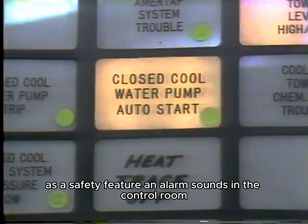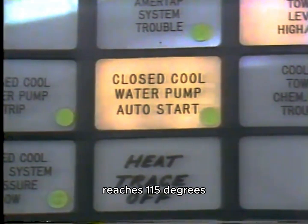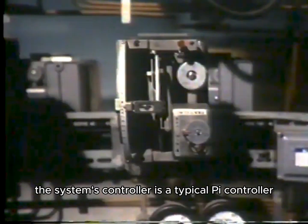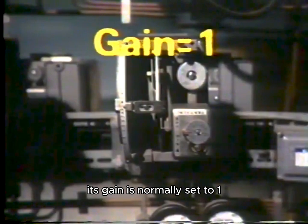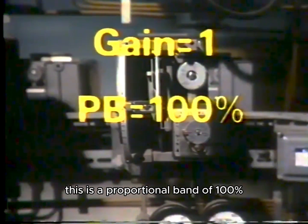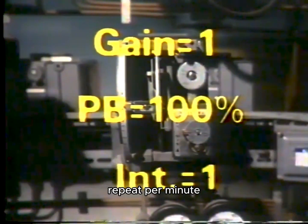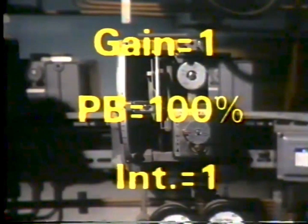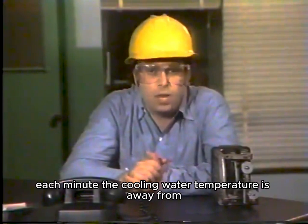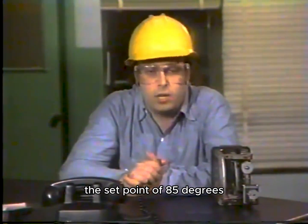As a safety feature, an alarm sounds in the control room whenever the cooling water temperature reaches 115 degrees. The system's controller is a typical PI controller. Its gain is normally set to 1. This is a proportional band of 100%. And the reset control is normally set at 1 repeat per minute. This means that the controller repeats the amount of proportional output each minute the cooling water temperature is away from the set point of 85 degrees.